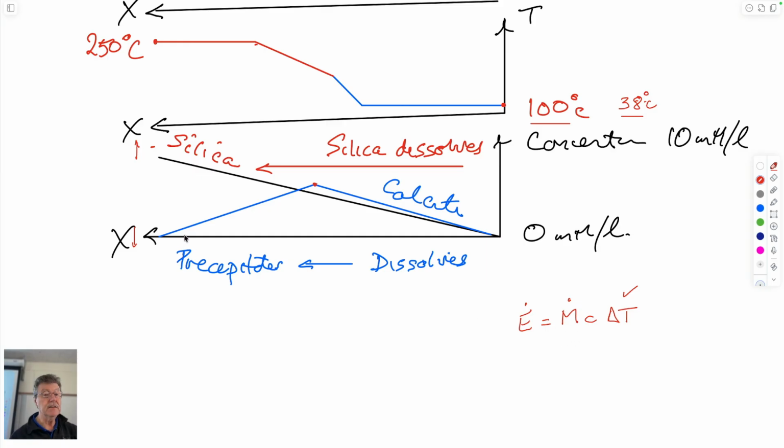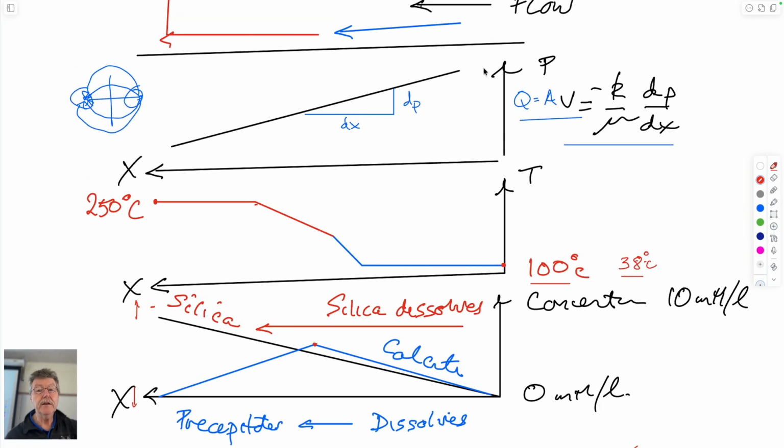If we precipitate calcite at the exit point of our reservoir, even if we've opened up pores and fractures at the injection well, this isn't going to be very good for maximizing our mass flow rate, because we can only apply a certain delta P across the reservoir. This delta P is limited by a maximum, not delta P, but a maximum absolute pressure before we hydraulically fracture the reservoir. And using a larger delta P means that pumping costs, parasitic costs, will be higher in running our system.